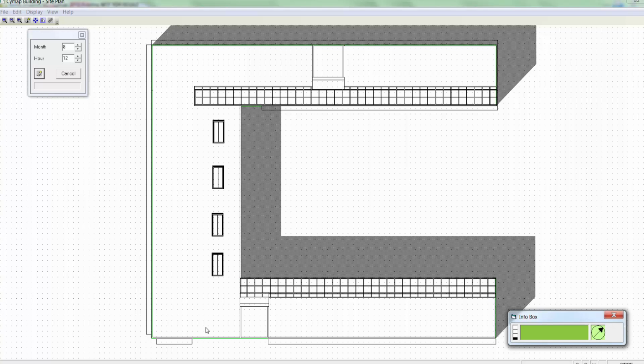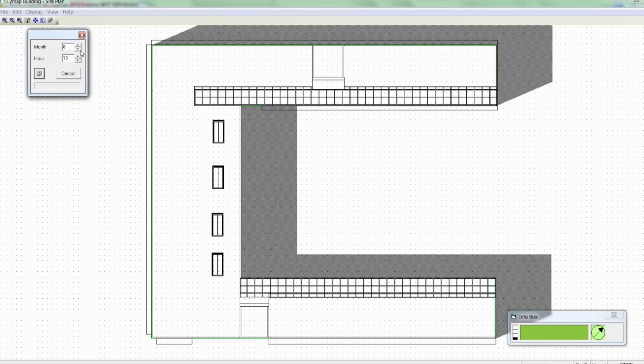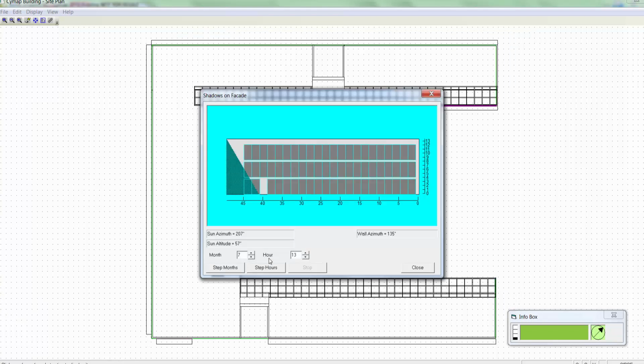Shading calculations can be applied by setting up the site plan for the building model so that shading can look at various hours of the day, various months of the year. Elevational shading can also be applied so the user can see how the shadows are cast across each face, and this of course will affect all the simultaneous loadings on the building in terms of cooling.